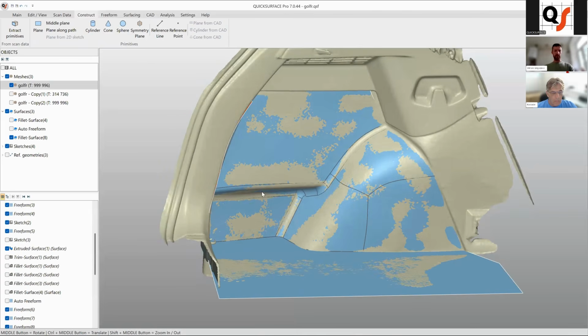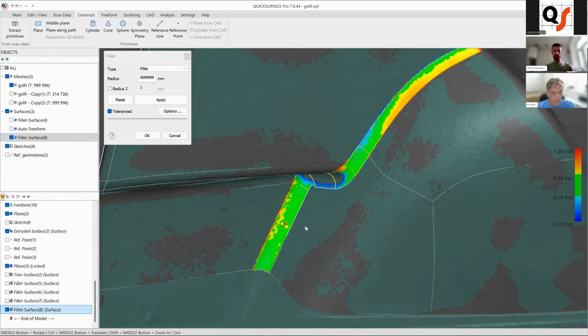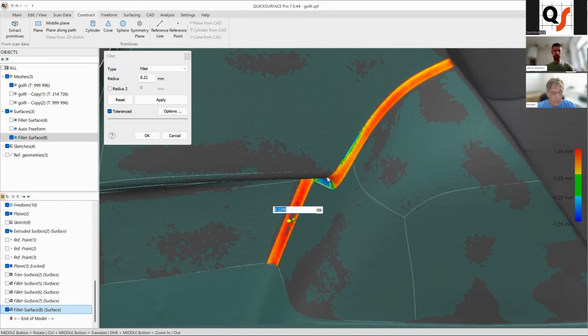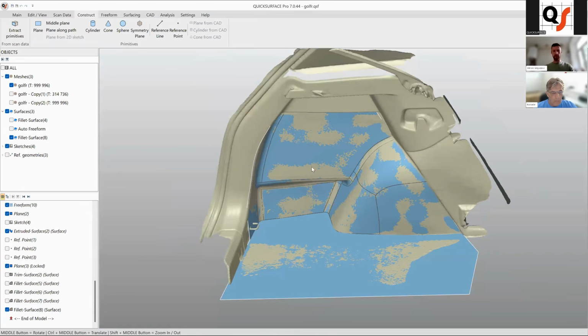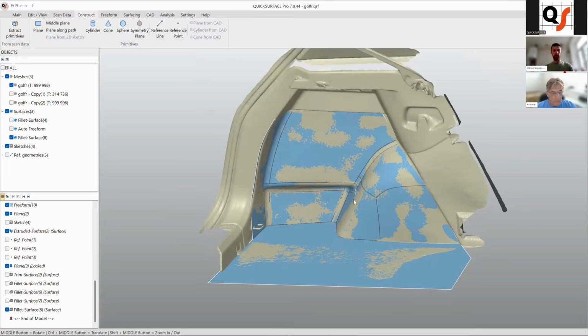Plus, in this case, you can always come back to any of your fillets and just change its value. We decided that you need it less or more, so you can always come over and change it rapidly. In case you had modeled this all as one, you wouldn't have this flexibility. It would be extremely difficult to actually change the fillet and do that constantly.